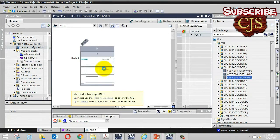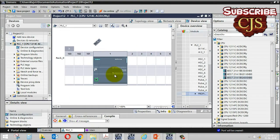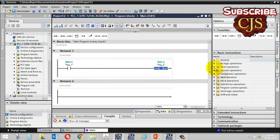Again, this is the simulated PLC. We are not actually using this PLC. Okay, so it may take a couple of seconds to add your PLC in your window. And this window is this PLC_1 window. Click OK, and this is your main window for programming. So your PLC is here. Now click on main again. So you're back to your program, and I think I may need to initialize my timer database again because I changed my PLC.